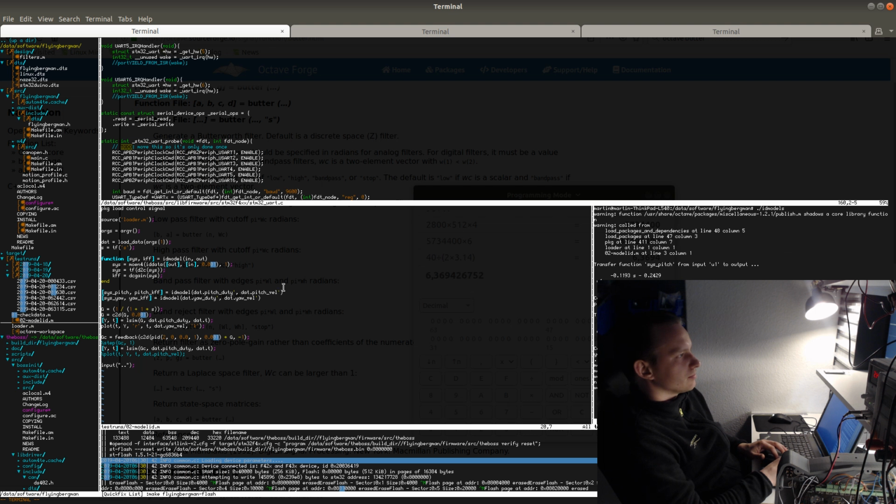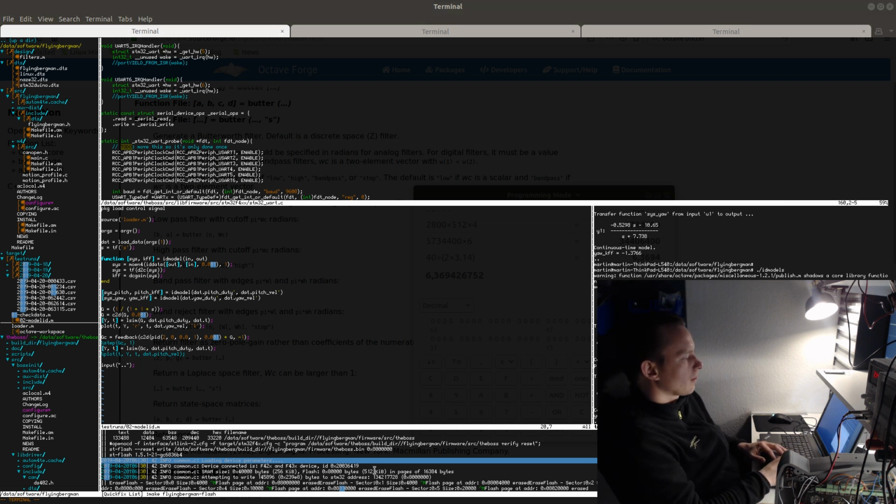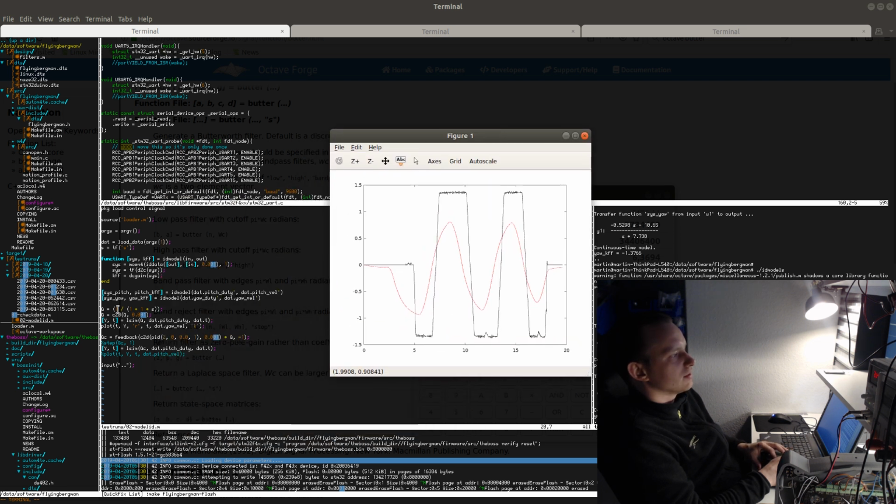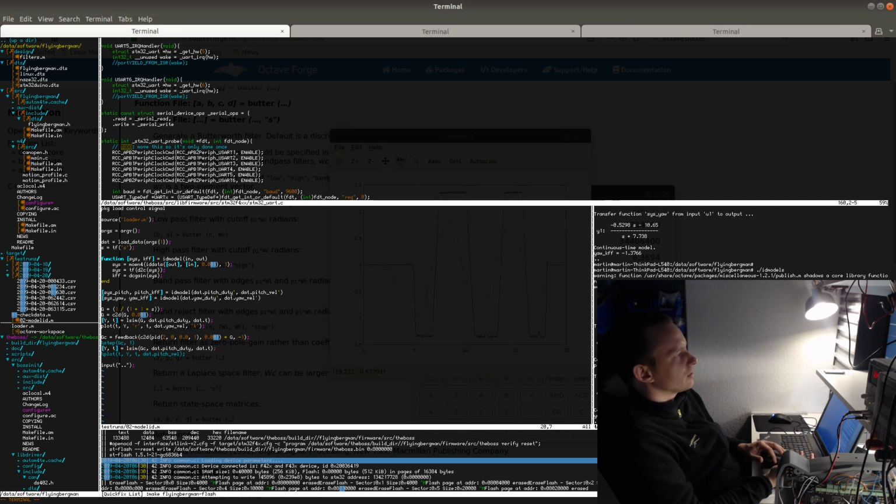Let's see, ID models. If we just use the unit gain and unit time constant, the simulated velocity of the motor ends up being this. And this is not correct. So what we want to do here is set the proper gain, which is basically the DC gain of the system. We can directly read this out from the system identification. The problem is that with system identification, we get a slightly more complex function, which has a complexity we don't actually need for controller design.